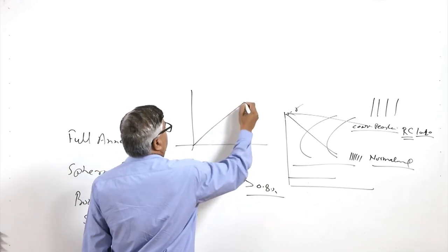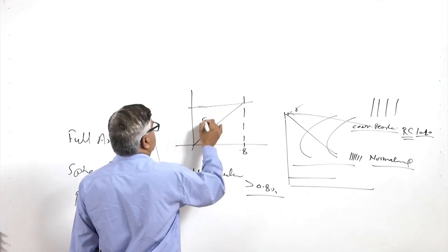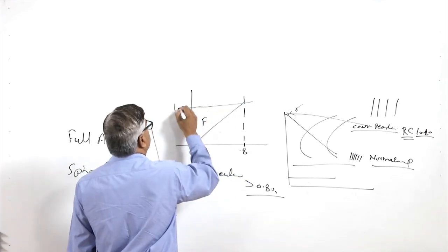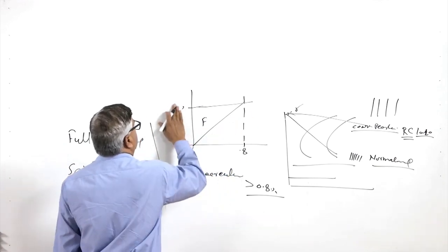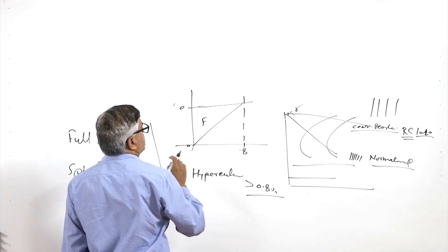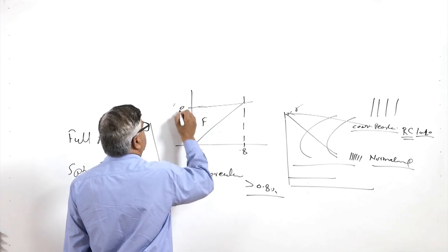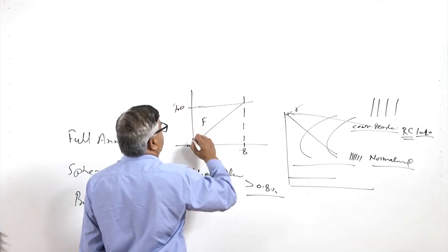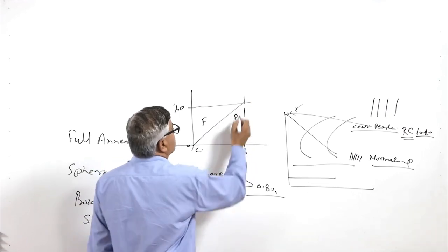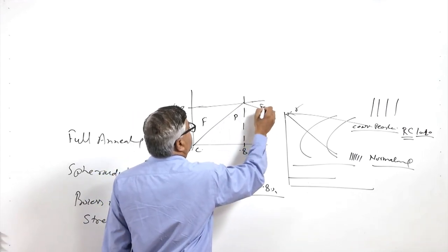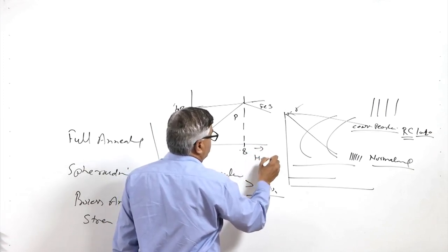we have 100% pearlite at 0.8, with the fraction of ferrite reducing; at zero carbon content it is 100% ferrite, and at 0.8 pearlite is 100%, and thereafter we see Fe3C. Fe3C starts appearing for the hypereutectoid steels.